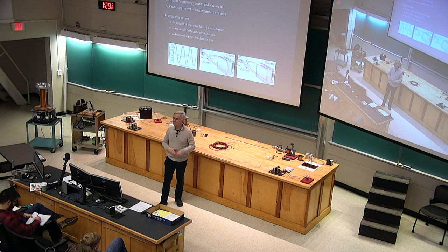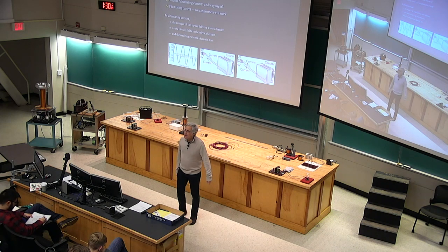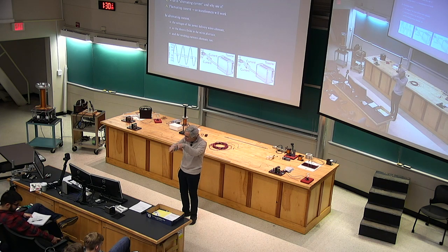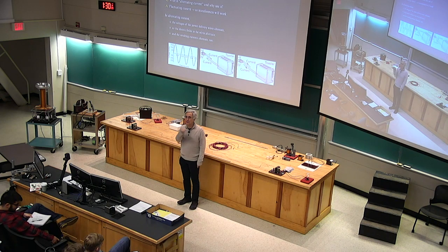This does have some effects on certain pieces of equipment that are sensitive to the rate at which that reversal occurs. I will also point out that there are moments when there is no voltage difference between the neutral and power, because power is on its way swooping through from positive voltage to negative voltage or negative to positive. There are moments when there is just no voltage difference and therefore no current in the wires at all.